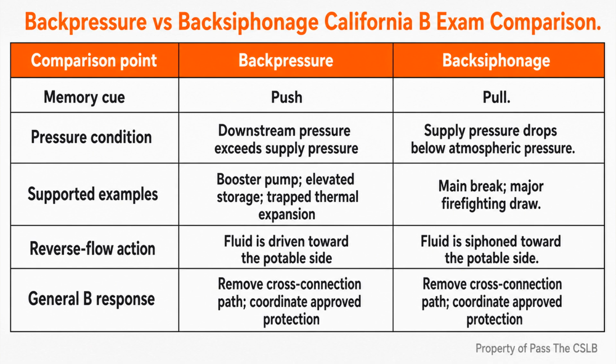An air gap has no springs, seals, or moving checks. Its protection comes from visible atmospheric separation. Mechanical backflow assemblies have legitimate applications, but device selection depends on the hazard, the approved design, the code, and the authority having jurisdiction.